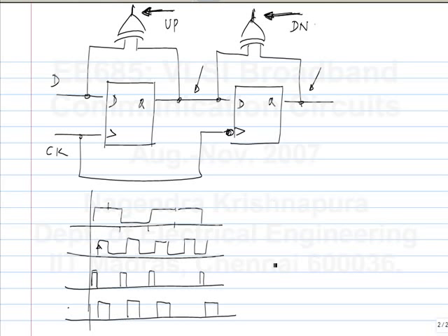In fact, in a way, it is better that it responds to the data edges because sometimes, because of ISI and so on, the data edges are not separated by integer multiples of the period. That you know from your simulations of ISI, right? Or the data itself can have jitter. In a frequency synthesizer, it should try and reject all of the jitter and give you a pure periodic signal. In this case, if the data has jitter, you had better track it. Because if the data pulse, instead of coming here, comes here, then the clock and data recovery circuit, instead of retiming it here, should time it here. So it should respond to jitter in the data also. So this aspect, which looks like reference feedthrough, is good for a clock and data recovery circuit. You want to track some of the jitter in the data.